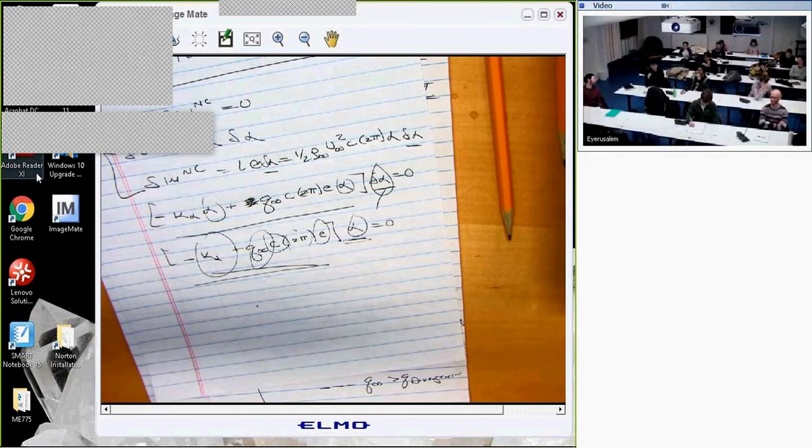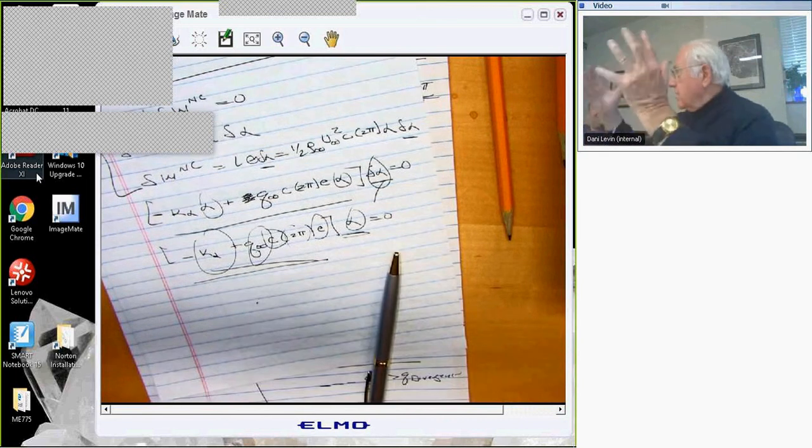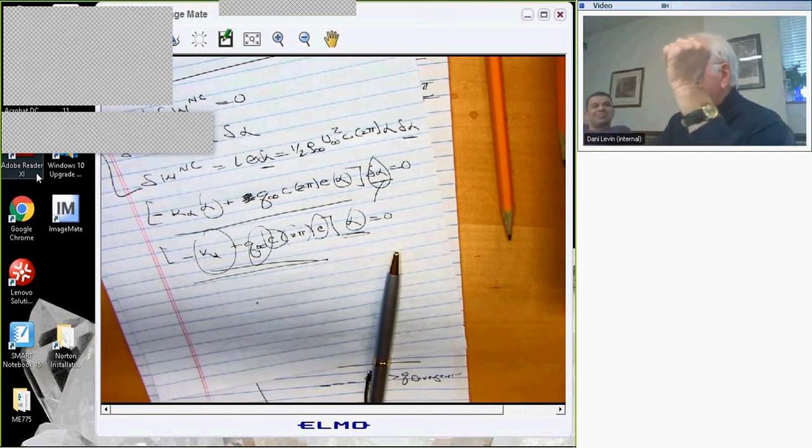Divergence, if it happens in a wing, does it happen along the chord or does it happen along the span? The answer is it happens everywhere. When you have divergence, then the entire structure is in a divergent state. It's not that one point in the structure is and something else is not. It's the entire system that is divergent.